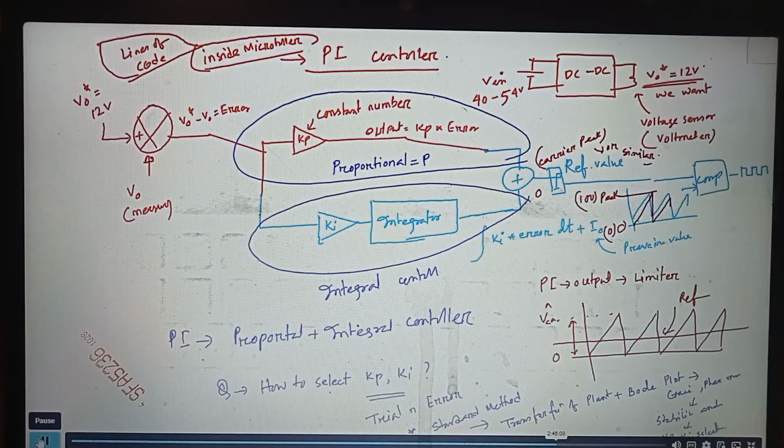Okay, so first, for this buck converter, you get a transfer function: output voltage versus duty ratio. Buck converter is a non-linear system. A lot of switchings are happening, right? So first you have to linearize it. So those, again, from a non-electrical background, most likely will be very difficult for you. Okay? Then you have to study a concept called the Bode plot.